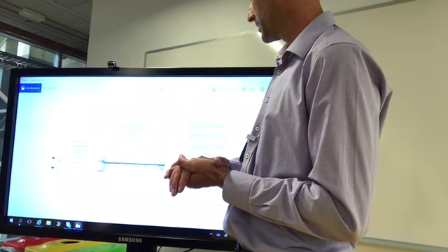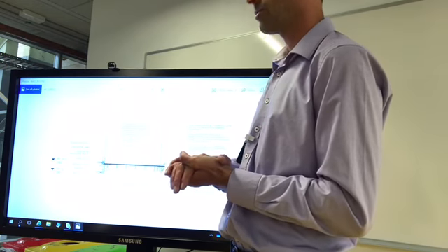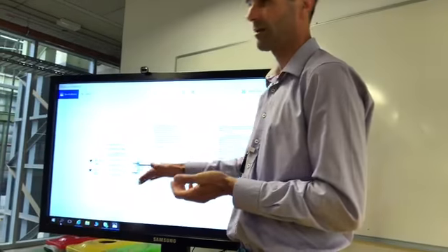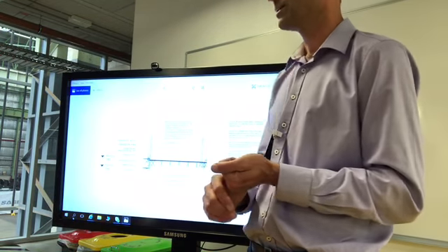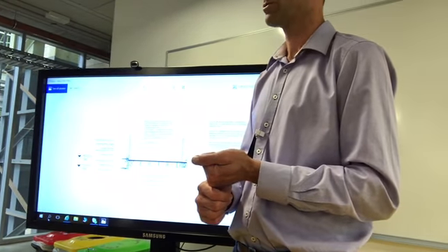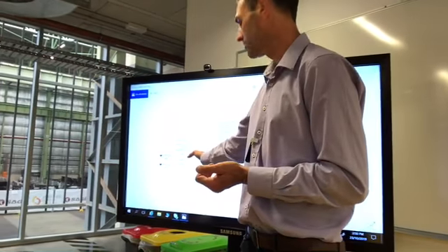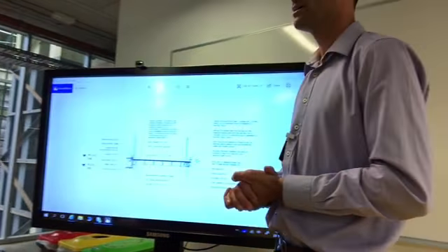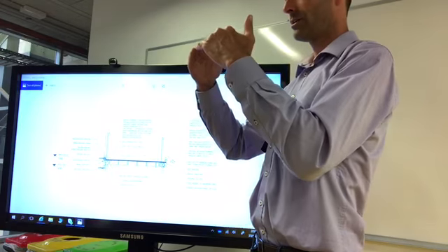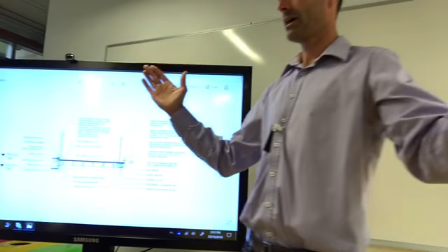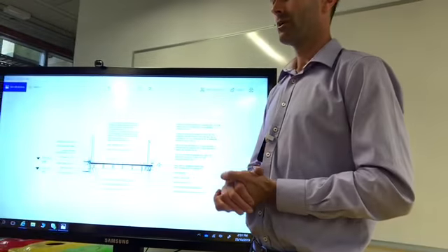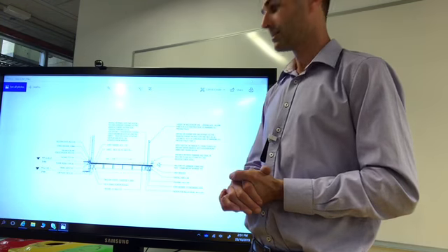One of the things that's going to be in a concrete floor balcony detail that's not in this one is your reinforcing as well. So you're going to be carrying reinforcing through. Once we get past this edge of the building here, we're turning it from a span into a cantilever. Our reinforcing details are going to be different in that regard.